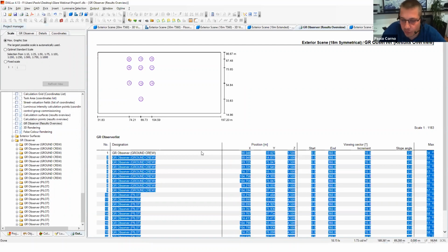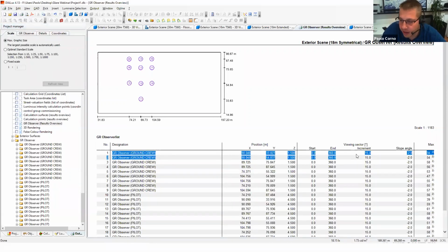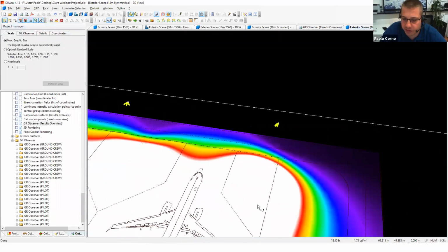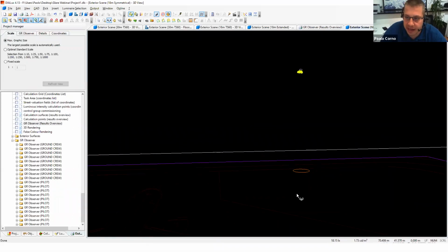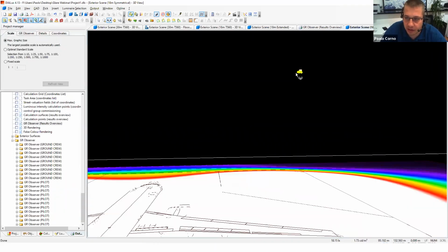You go from a spot here, walk just a few meters, and your glare rating will jump up by 20 in the span of about 9 meters. What happens is that you create hotspots. If you're sitting in a certain position, you get hit with the highest peak of candelas per kilolumen by one luminaire, which is going to glare you a lot.